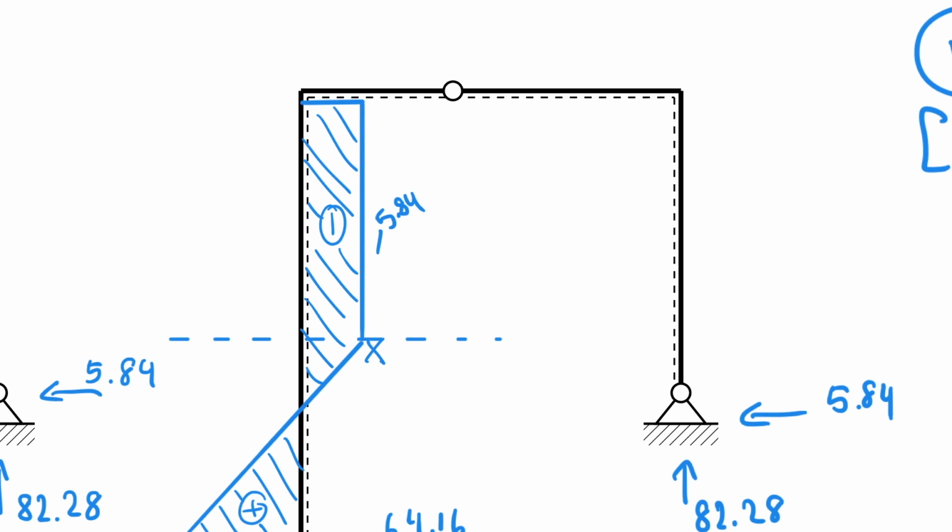So let me draw that. So this here would be negative 2.28. And then I go down by 40 for every meter, right? So I go down, down, down until I hit the hinge, because that's where the evenly distributed force ends. And if I go down with 40 over that distance, I end up as minus 87.28.